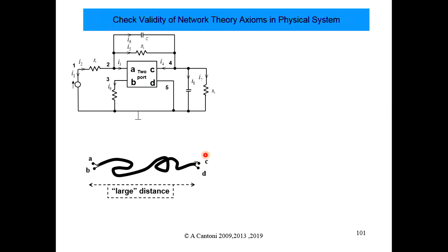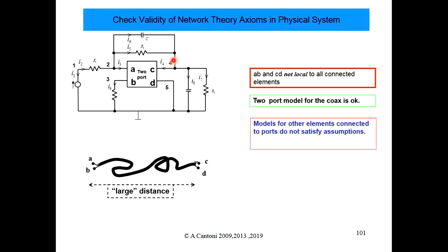So we couldn't use circuit theory to analyse that particular circuit, because there's a large distance between the wires connecting that resistor. It's large compared to the wavelength of the signals of interest. So we've got A and B, both local to themselves, and we've got a 2-port model for it, but they're not close to each other, and we have direct connections between the two.